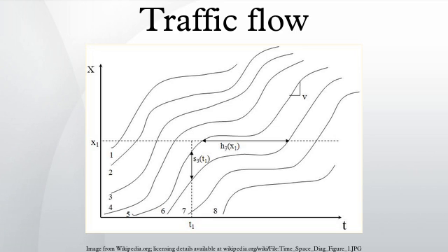The engineering approach to analysis of highway traffic flow problems is primarily based on empirical analysis. One major reference used by American planners is the Highway Capacity Manual, published by the Transportation Research Board, which is part of the United States National Academy of Sciences. This recommends modeling traffic flows using the whole travel time across a link using a delay flow function, including the effects of queuing. This technique is used in many U.S. traffic models and in the Saturn model in Europe.